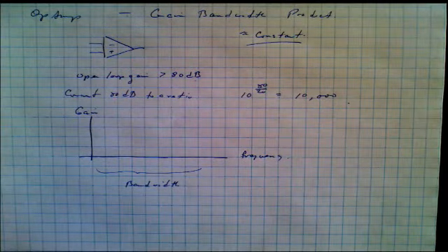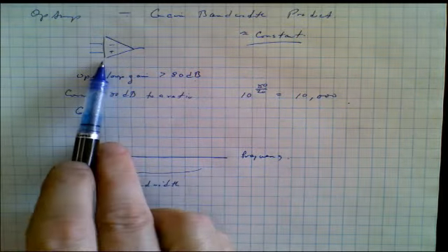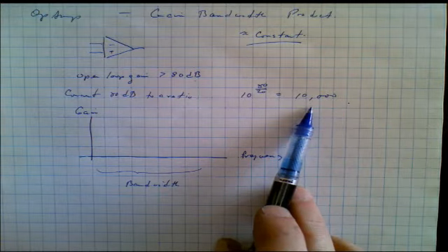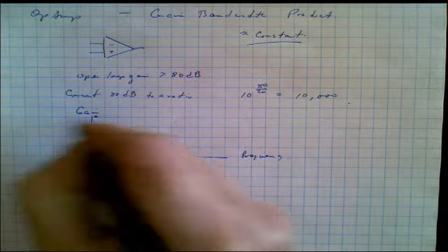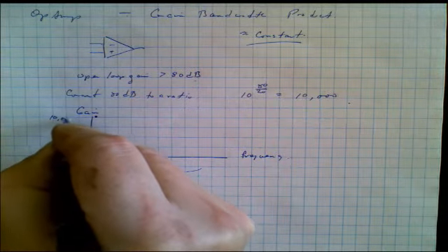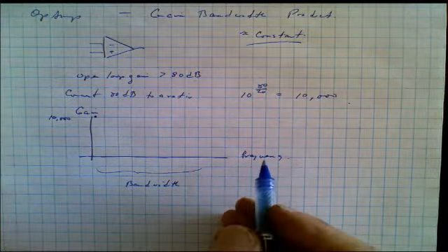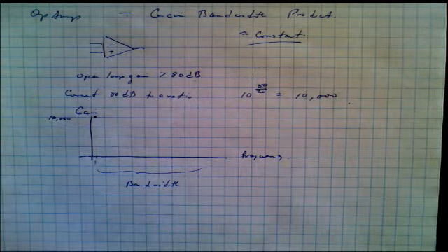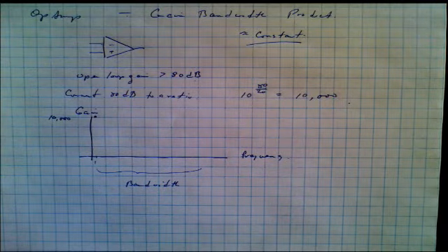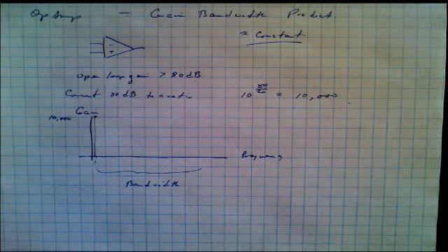Now, what does that tell us? Well, that tells us that if we use this amplifier as it is right now, with a gain of 10,000, so let's just put a plot up here. There's a gain, a very high gain, it's 10,000. Then the bandwidth, or the frequency, would be simply 1. It would have a very, very low bandwidth. We could only use it in this narrow little range of frequencies, so it wouldn't be much use to us.